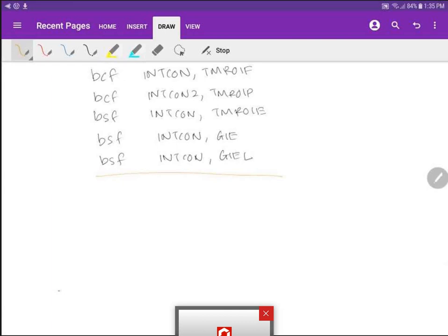This is the main program. But what are you missing now? What configuration do you need to do? What subject are we learning now? I don't like micro PE. Stop topic. What are we learning about? Timer. What should we do with the timer? We should configure the timer, right? That's what you did the calculation for. So you configure the timer to generate 0.5 second, right? So you need to do that configuration here.